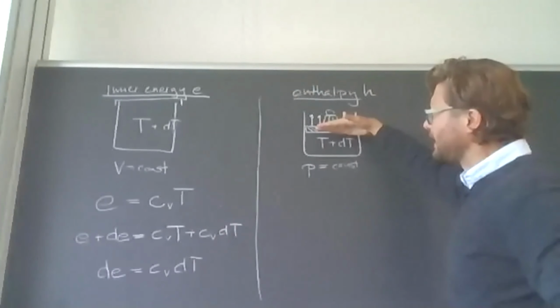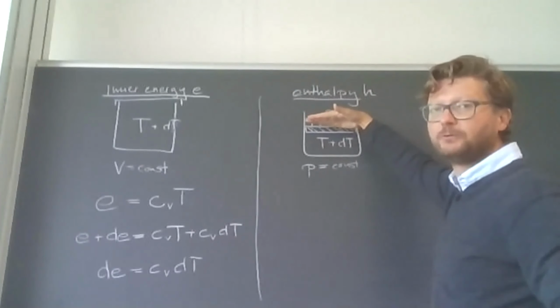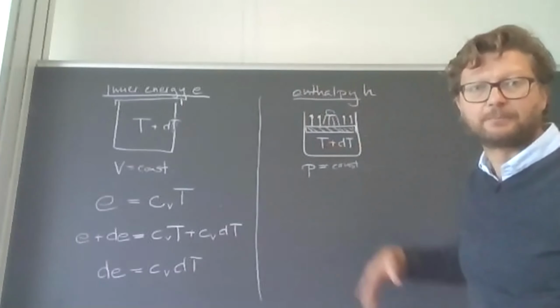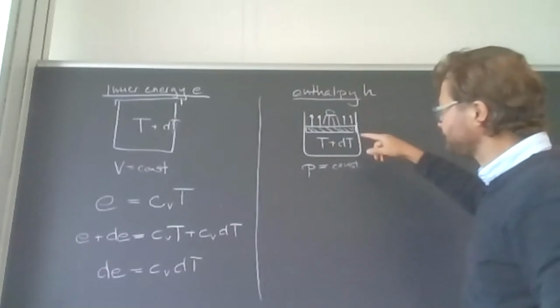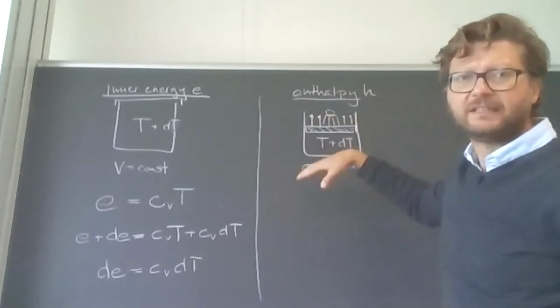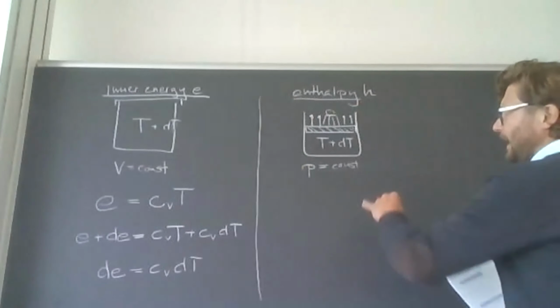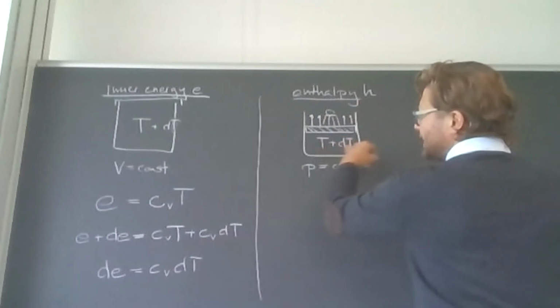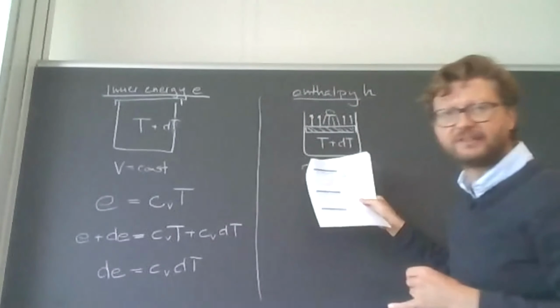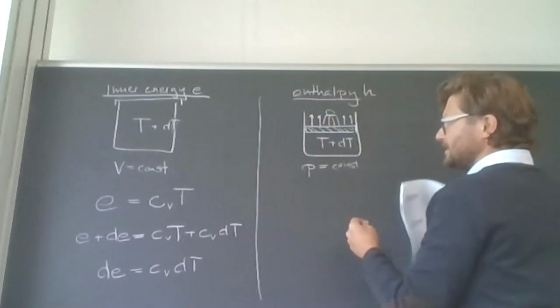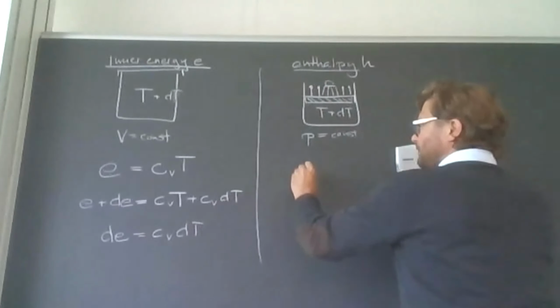And that work is related to the increase in volume times the pressure, right? That's the power or the work that we're doing. And of course, the increase in volume will decrease the density. And this effect, so the increase in inner energy just by increasing the temperature plus the mechanical work done, is contained in the enthalpy.